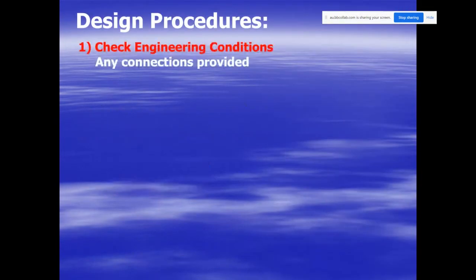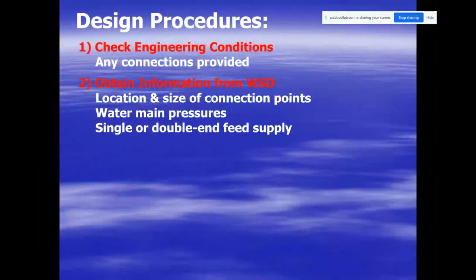Now let me reiterate the design procedures. Even as designers, you need to check the layout from the floor plan for diversion. Where is the main water pipe? Where is the main discharge drainage pipe? And then locate the supply. I recommend double end because if the right hand side freshwater system gets trouble, then you can use the left hand side, the other way of the water supply.